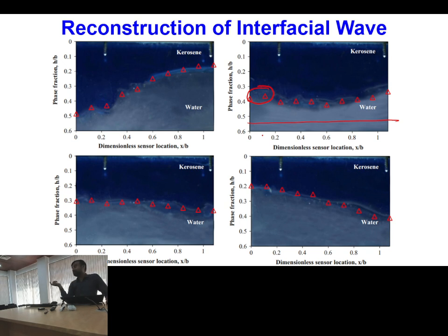So that is something you need to do: you need to actually control the RPM. If you do rotation at a very controlled RPM, then what will happen? There will be phase stratification depending upon the density in a paraboloid manner. But if you start rotating at very high speed, then what will happen? There will be intermingling between the phases and then bubbles will form.